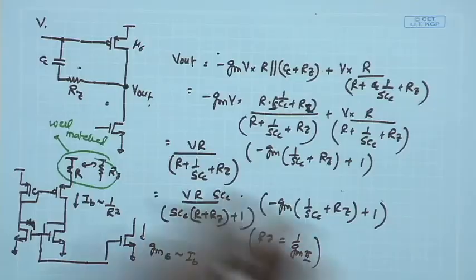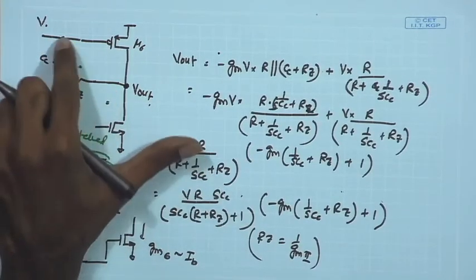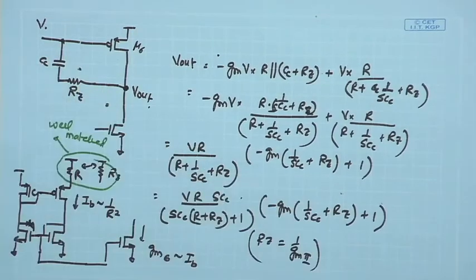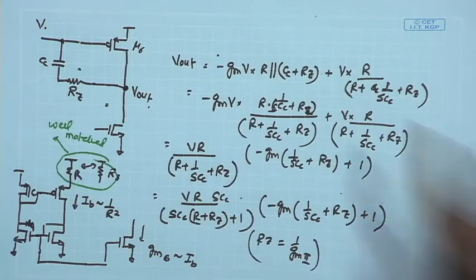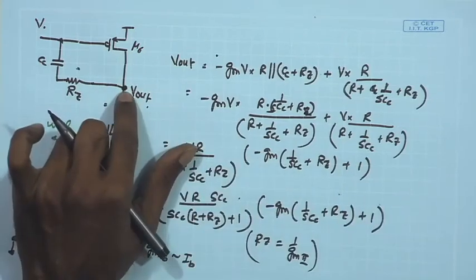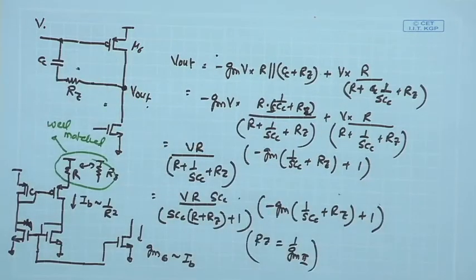So, what about noise in RZ? RZ in general is in the shunt path once again, and it is in the second stage. So, if you look at the overall amplifier, the noise is dominated by the first stage, and this is appearing at the second stage. So, that basically suppresses its effect on the overall output noise. Moreover, it is providing something similar to a shunt feedback, just like we have for the main amplifier. There also we have discussed that if the feedback resistor RZ or RF that we had in the op amp has a shunt configuration, the current noise contributed by that at the previous stage is relatively small. As a result, it is not going to have significant impact.